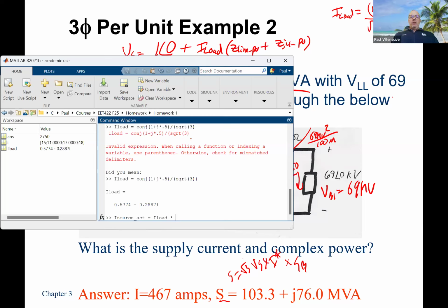That's going to be equal to 100 E6, which is 100 MVA, and I'm going to divide 100 E6 by the voltage at that end. So that's going to be equal to 138. Is it 138 kV? I think it's 138. But don't forget, I still need to multiply that by the square root of 3.